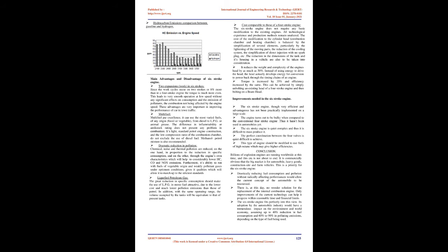Heat passes from the combustion chamber to the air heating chamber. The wall of the combustion chamber allows transfer of heat to the air heating chamber, which heats the air under high pressure, which is eventually used in the 5th stroke. The burning of the fuel does not have any direct influence on the piston. The energy released by the combustion passes through a valve which enters the cylinder and hence work is done on the piston. Working. The working of the 6-stroke IC engine is very similar to the 4-stroke IC engine. The first 4 strokes remain the same with the addition of 2 more strokes discussed below.